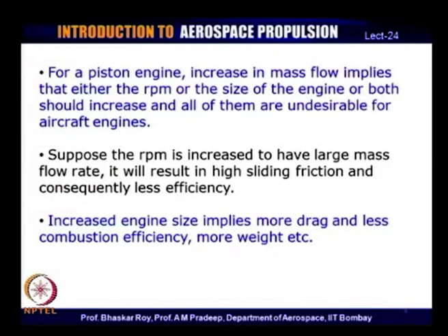Now, suppose you have an increased RPM to create large mass per unit time. This will mean that the piston would be moving up and down the length of the cylinder more frequently, and as a result it will actually encounter more sliding friction. As a result there will be friction losses, which we shall be talking about a little, and as a result there will be loss of efficiency.